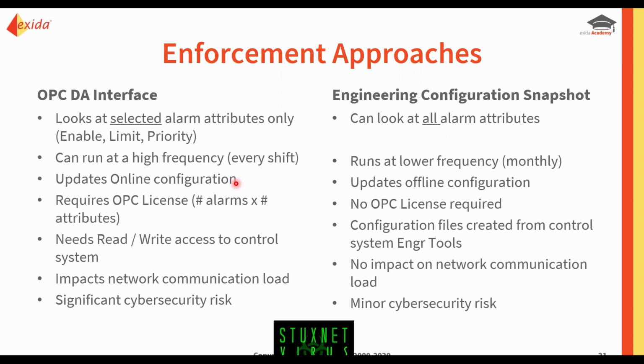The OPC interface is really connecting with the online running system. So it requires an OPC license to work. You would need to get a license that takes into account the number of alarms times the number of attributes for each alarm. Remember, that could be 10 to 20, depending upon your system. And you need read-write access to the control system. So this will impact your network communication load on your HMI network, and it does open up a significant cybersecurity risk that needs to be handled.